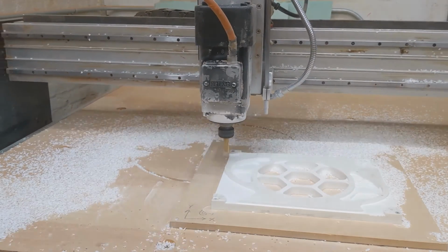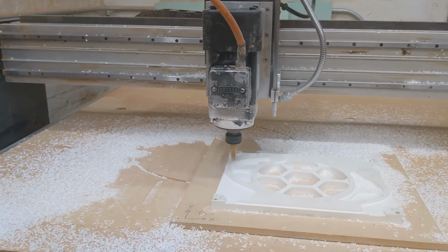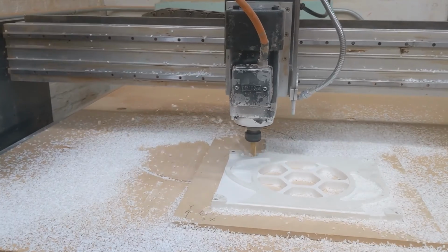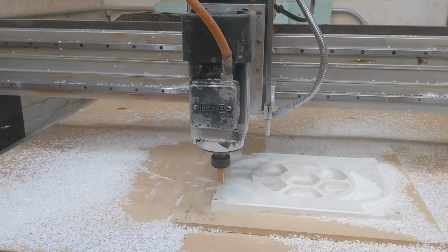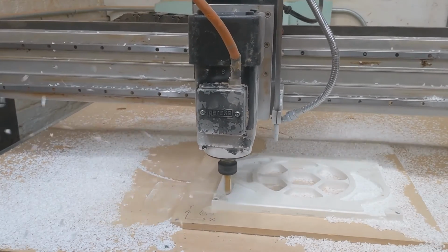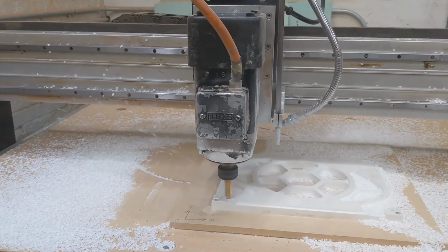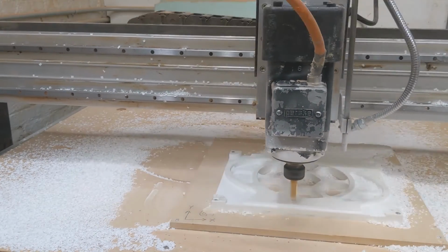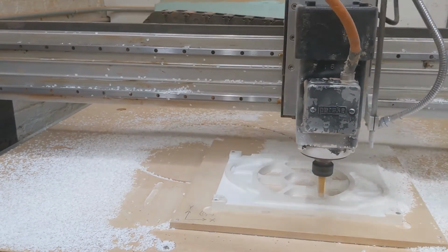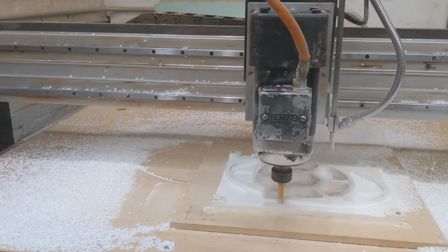I had one more thing to say before I shut up and just let you watch the rest of this machine, which is that if you're wondering where to start with feeds and speeds, you can hardly go wrong at 60 inches per minute, and maybe even up to 100 inches per minute, but maybe start with 60. I actually don't have much experience with this machine yet, so I'm not sure what it can pull off. As far as width of cut, 1/3 diameter or less is great.